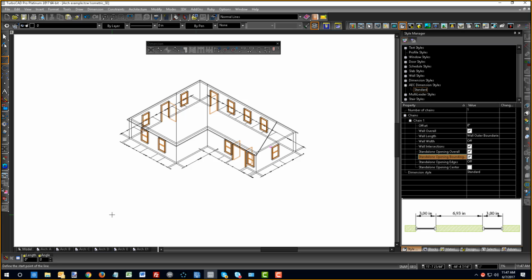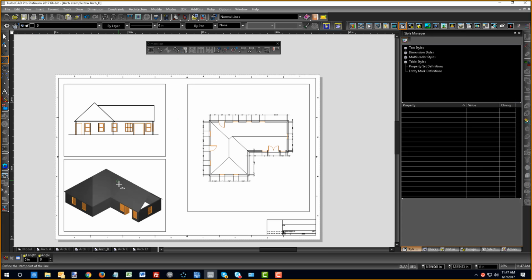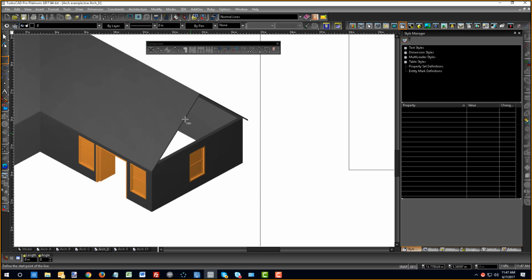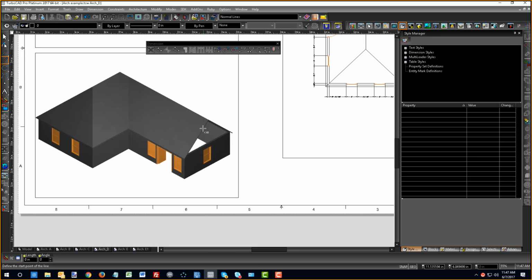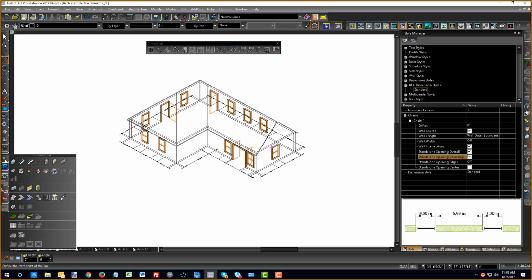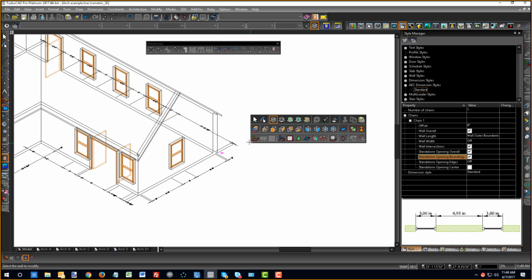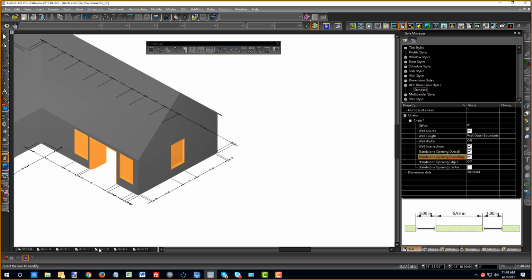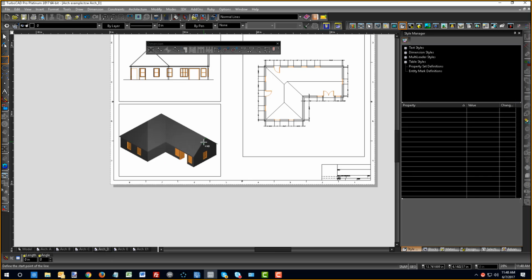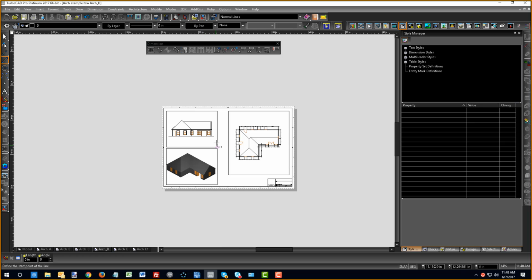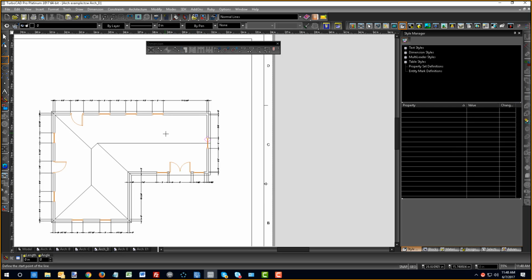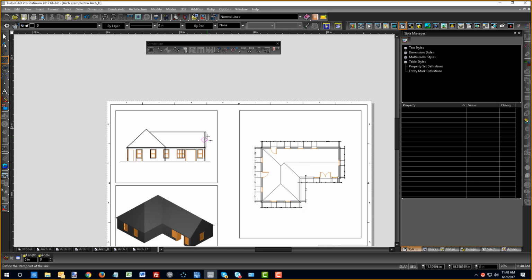There. Did I finish? I'm surprised that roof went away. Oh, no, it was a refresh problem. So now we see the hole there. TurboCAD does have a way to fix that. Let me just show that. That is a pro-only feature, and that is the ability to create a wall modifier. So I'm going to choose the wall segment, and then I'm going to choose the roof segment, and that's going to clean that up automatically. Let's go back to our paper space, and we see now that that's looking correct, as are the ends on these other two viewports.